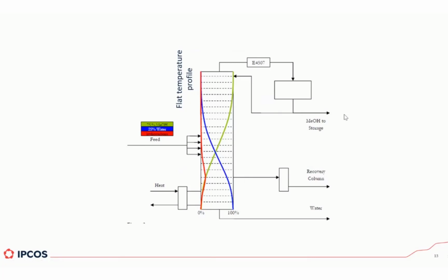A methanol water mixture with 10 ppm of ethanol or water, or with 20 or even with 100 ppm, will most likely have almost exactly the same boiling temperature, which means that for most of the trays, I think it was the first 30-something trays, this column had in total 120 trays, if I recall correctly.